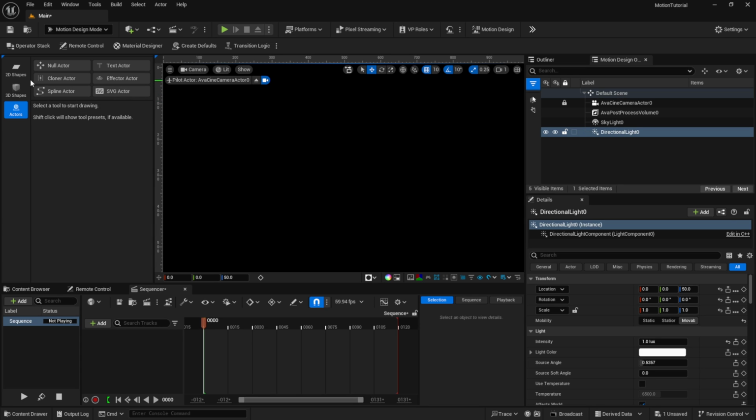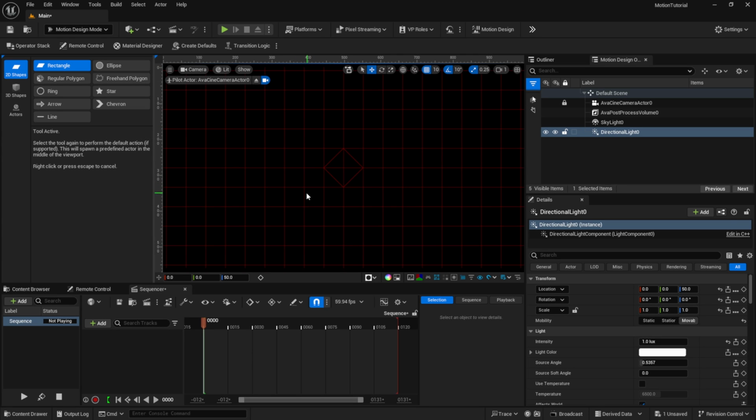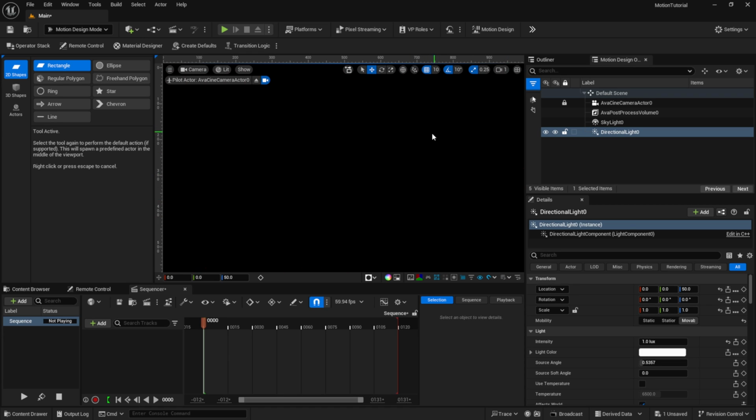But for this tutorial, we're going to focus on the 2D stuff right here, in which let's start by building out a rectangle. So if I left click on this, you notice that we get this red grid in here, and this is for if we want to draw in our shapes. Now, if you want to turn off the grid, if you come down here in the lower right hand corner where it says toggles grid on and off, you left click on this and that's going to turn that off.